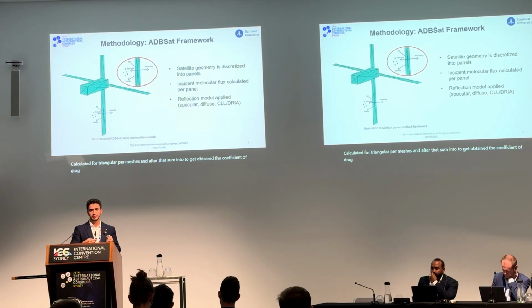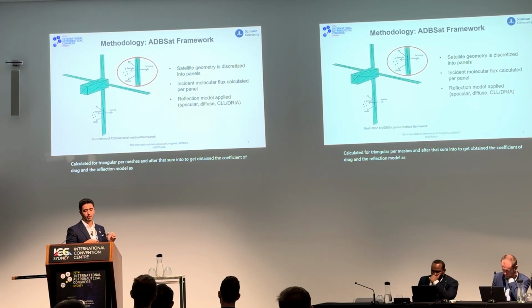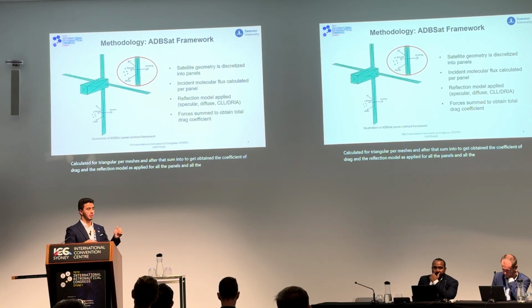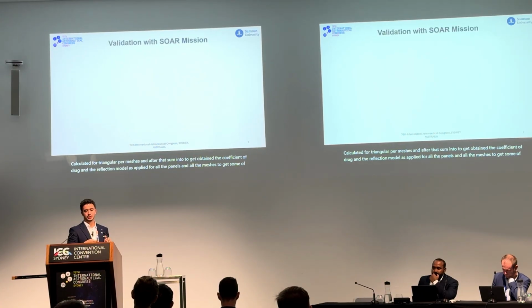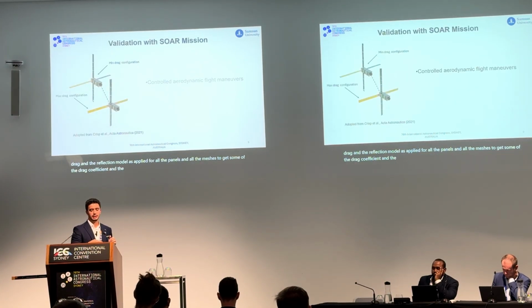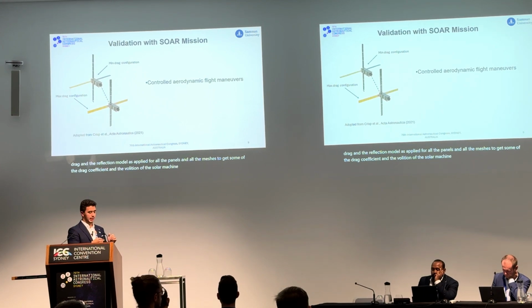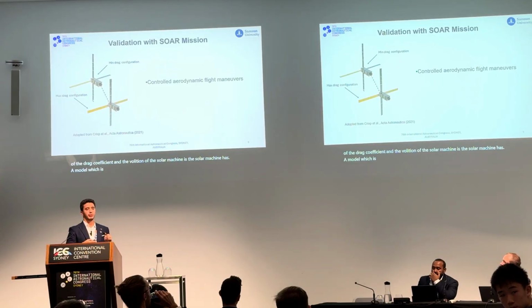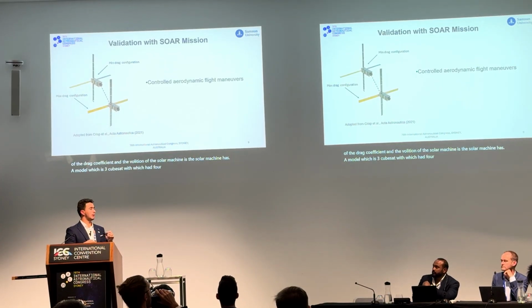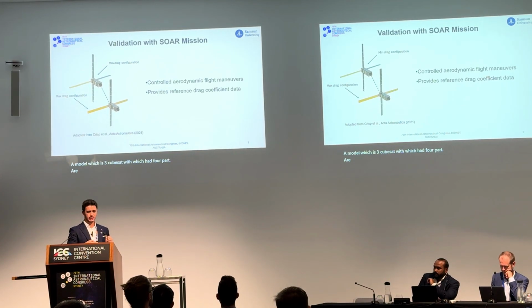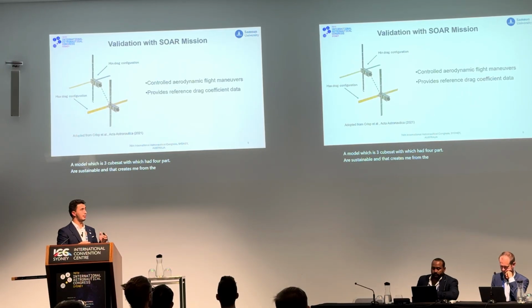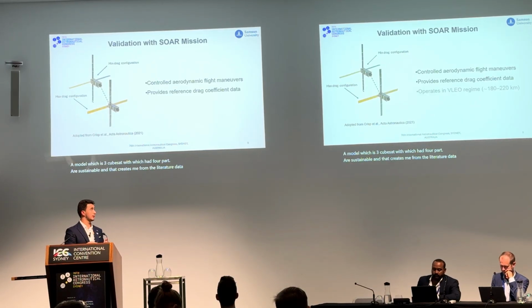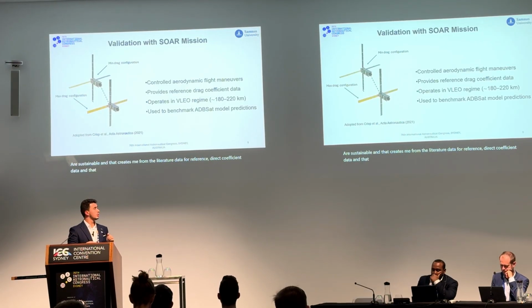The reflection model is applied to all the panels and meshes to get the total drag coefficient. For the validation, the SOAR mission has a 3U CubeSat with four stable panels, which gives me reference drag coefficient data from the literature, and I focused on 200 kilometers.